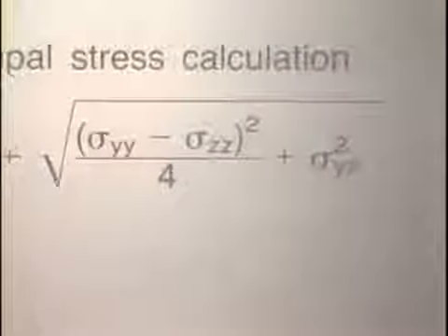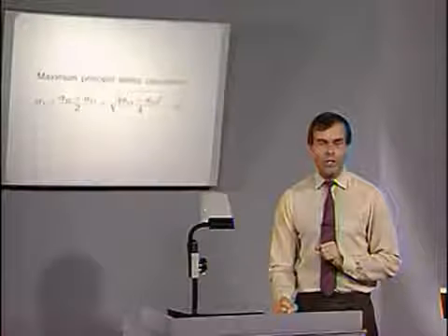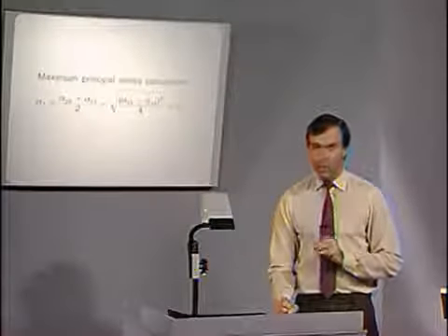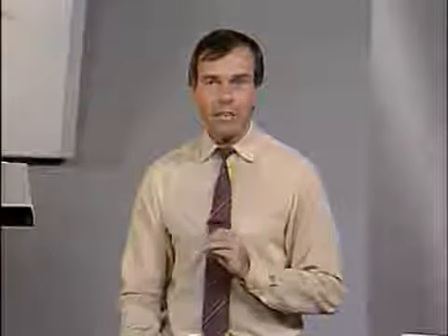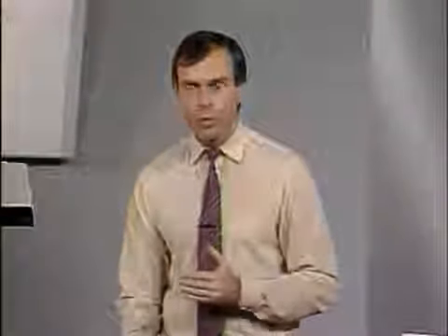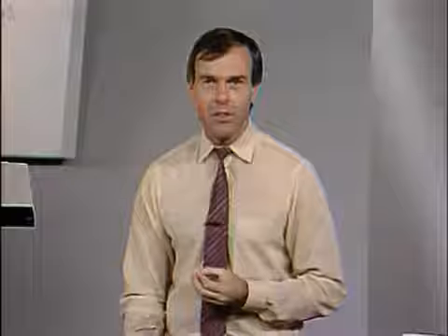We can ask ADINA-PLOT to calculate sigma 1 at all the nodal points in the mesh, and then to search through those sigma 1 stresses to find the location, the element and the nodal point, of the maximum stress occurring in the mesh.